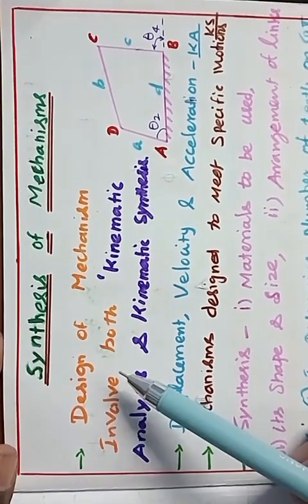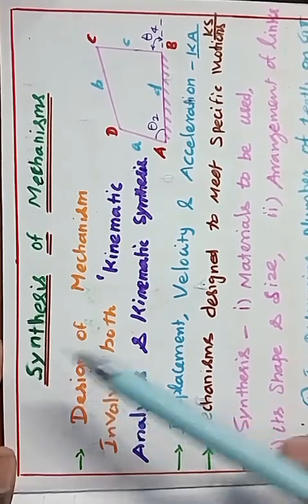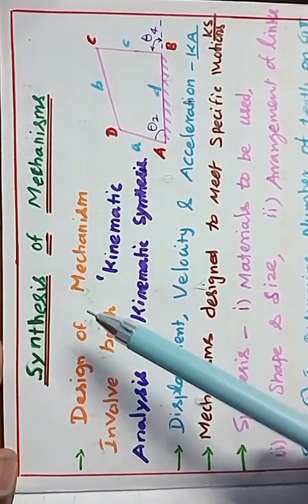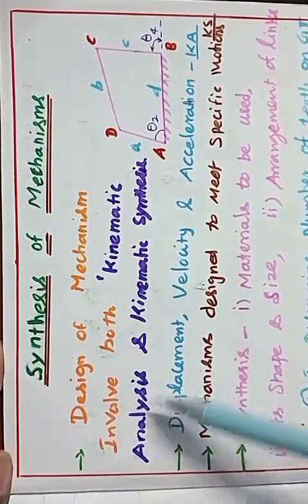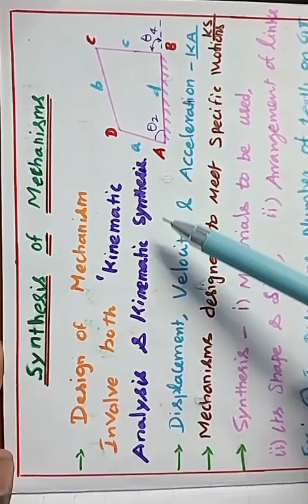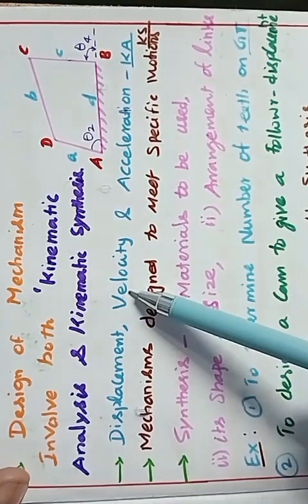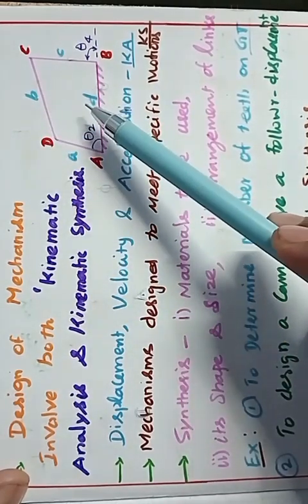Welcome to Casting Academy. Today we are going to discuss the synthesis of mechanisms. Design of mechanism involves both kinematic analysis and kinematic synthesis. In kinematic analysis, displacement, velocity, and acceleration of the various parts of the link are to be determined.